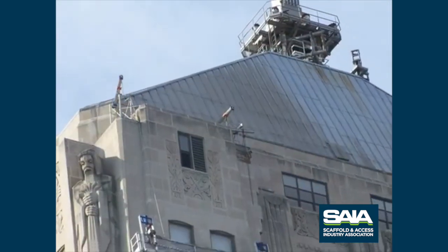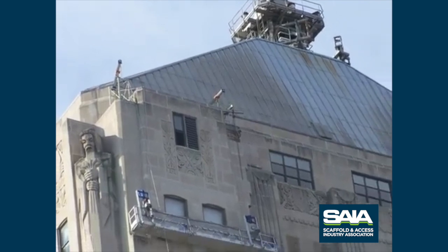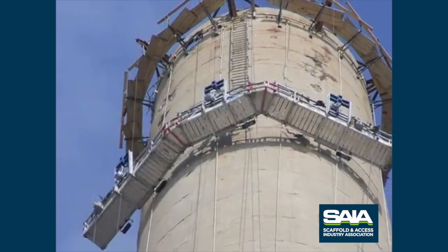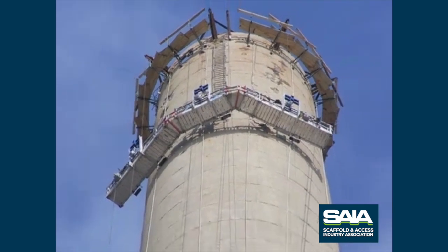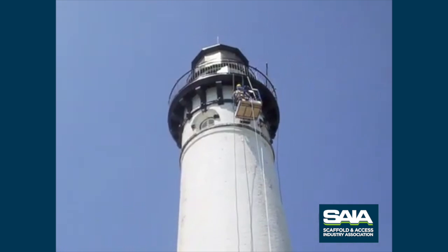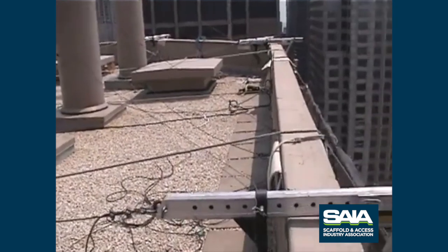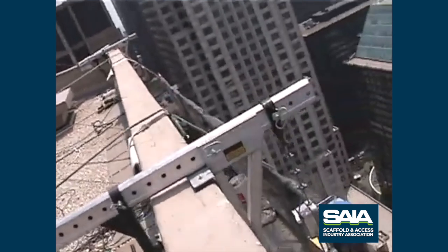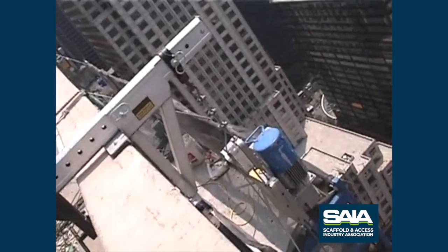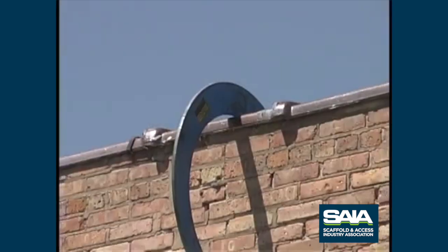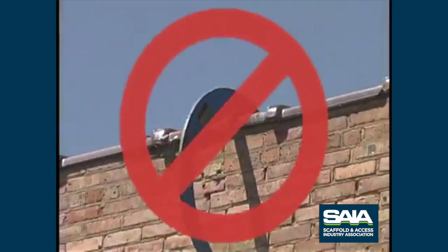Rooftops, vessels, and structures create various challenges. A qualified person needs to determine equipment needed and locate suitable anchorages for fall protection equipment. Structural parapet walls must be capable of withstanding the overturning loads imposed on them with a safety factor of 4. A qualified person must evaluate the parapet.